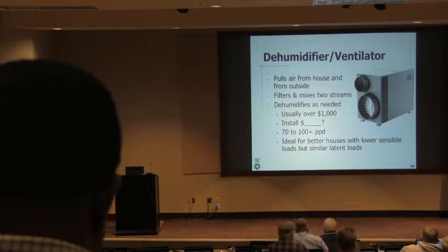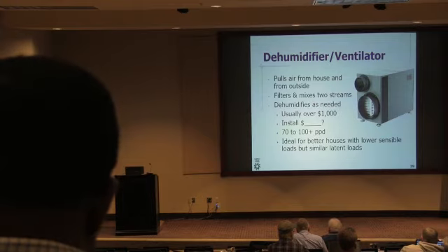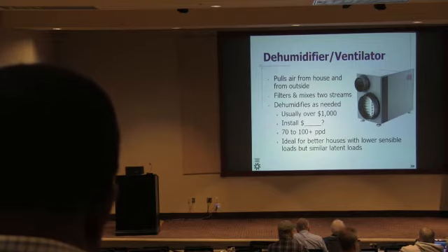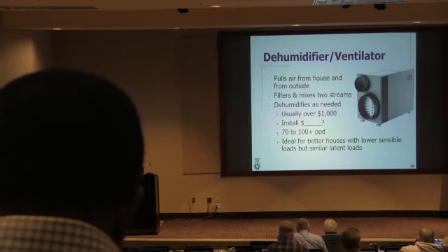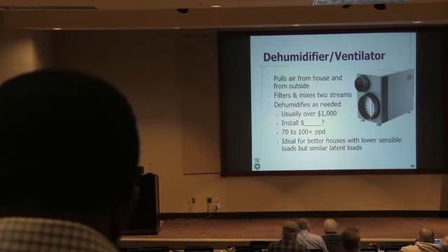I think they most often install these using the return and supply of the home, so you would get some return from mixing and some dehumidification inside. But it's primarily dehumidifying the outside airstream for ventilation. But I think it would improve the overall humidity comfort in the home.